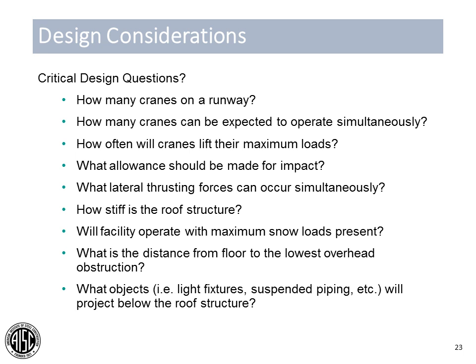Sometimes owners have multiple cranes within one runway, and one is identified as a maintenance-only crane. However, if that crane is able to be operated during the same use period as the primary crane, you may want to consider both cranes operating simultaneously. You should discuss with your owner how often will these cranes lift their maximum load. What allowance should be made for impact?